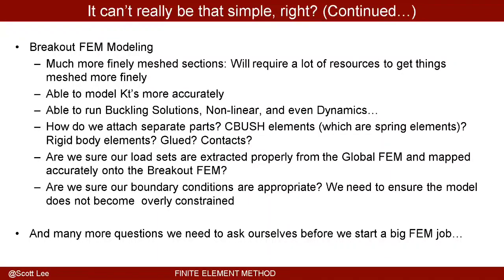And as I mentioned before, how do we attach the separate parts? Do we want to spring them off with CBUSH elements? Do we want to use RBE2s, RBE3s, rigid body elements? Do we want to use glued contacts or just normal surface contacts? Are we sure our load sets are extracted properly from the global FEM, and are they mapped accurately onto the breakout FEM? That's not an easy procedure, so you have to make sure you do all that right.